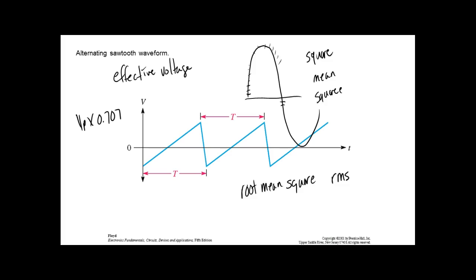If you measure AC waveforms that are not sine waves, then these meters right here are going to measure the wrong value. So we have meters called true RMS meters. Have y'all heard of those? Cost a lot of money. But they literally calculate the root mean square. So they have a microprocessor, they have a computer inside of it.